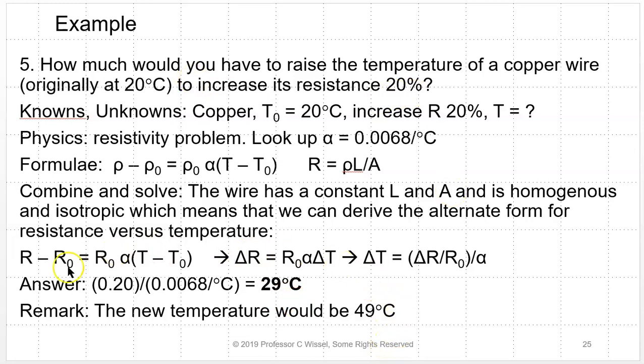Now, in this kind of problem, people make this mistake all the time. When they ask you for the final temperature, don't forget this is a change. So you had to add the 20 degrees C to get the final temperature.